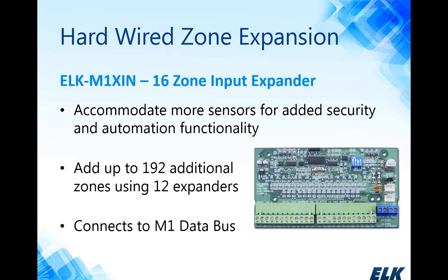Now the M1 system is flexible as far as 4-wire smoke detectors. Any zone on the system, including input expanders, will accept a 4-wire smoke detector.